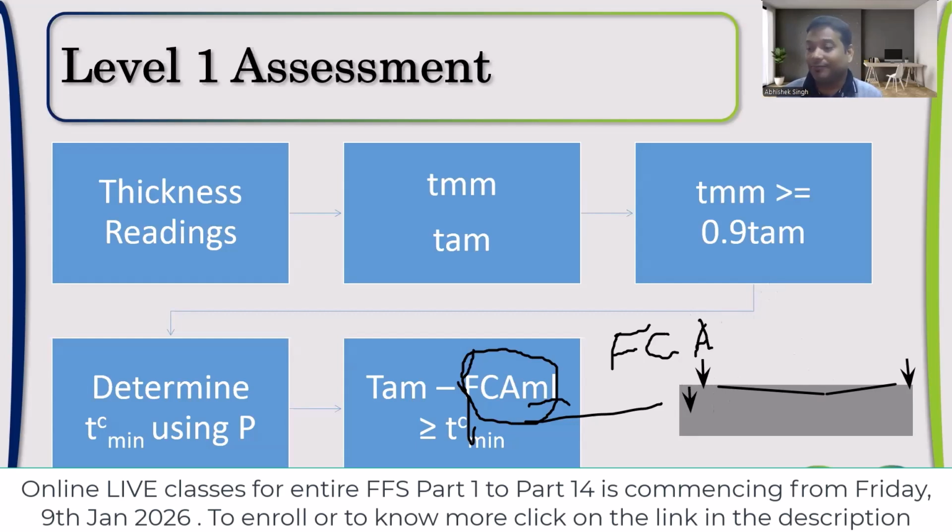After doing the inspection in the 5 years, when we read the data, do we have the idea what has happened in the last 5 years? Do we have the rate? Can we calculate the rate at both good thickness and the local or general metal loss location? Yes or no? We can simply subtract the thicknesses and divide that by the number of years. That is the rate, isn't it?